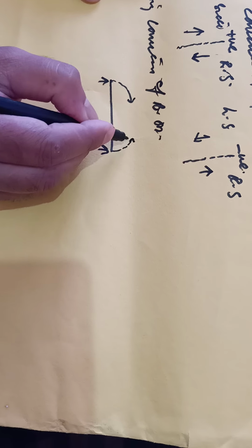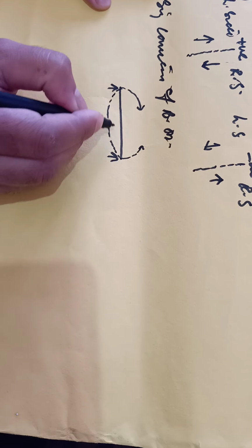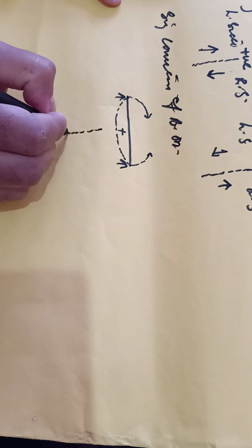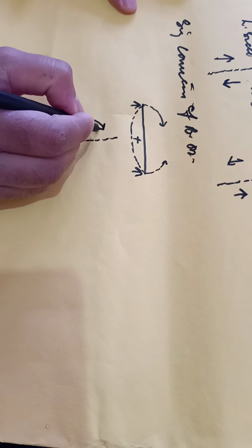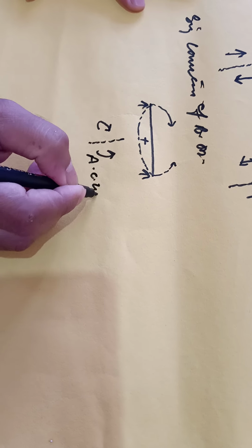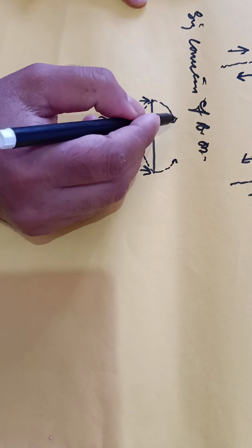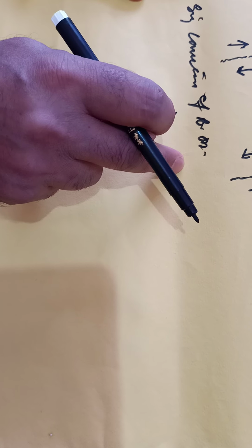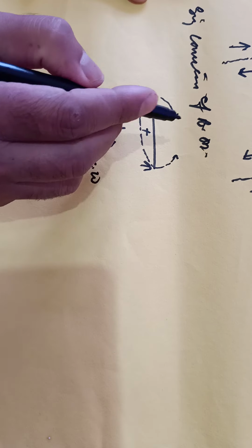In this way, this bending will take place. Simply, clockwise if left of the section, if we do sectioning simply in this way. If it is in clockwise direction on the left hand side and anti-clockwise direction on the right hand side, then it is positive.